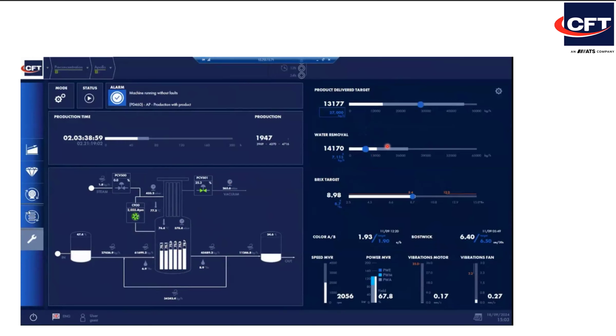In this case, the machine was designed for roughly 30,000 kg an hour. The nominal capacity is the light gray line, while with the white line we see the current evaporation capacity of the line, which is down to 14,870 kg an hour, so roughly 40% of the nominal capacity. The blue spot represents the set point defined by the operator.